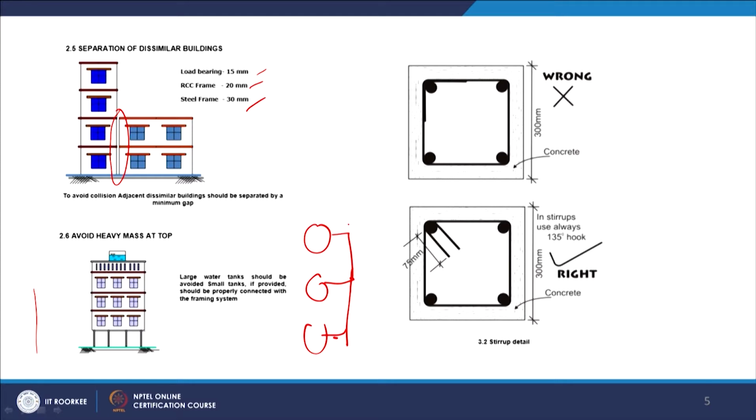Also, these technical manuals talk about the type of reinforcement and the connection details. For example, they talk about when we say a 1 feet beam, the reinforcement, how the stirrups and the clear cover have to be done. The stirrup details also have been given as guidance, how to mould them, what to do and what not to do.